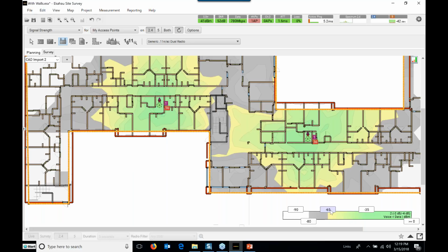But if you really want to see how that client's seeing it, it's useful in troubleshooting scenarios where you think you've got a good design, but you've got a finicky client that's having trouble. No other type of client's having issues, but this one client type is. You can model for that client, and maybe it was a good design in the past, but this new client is finicky, and you've got to change your design a little bit, which could mean tweaking the power settings on the APs, moving the APs around a little bit, or even adding APs. But being able to visualize from the client side is going to help you locate where you need to make that change in the live environment, or in your prediction prior to deployment, a lot better than just dealing with the raw signal strength would.